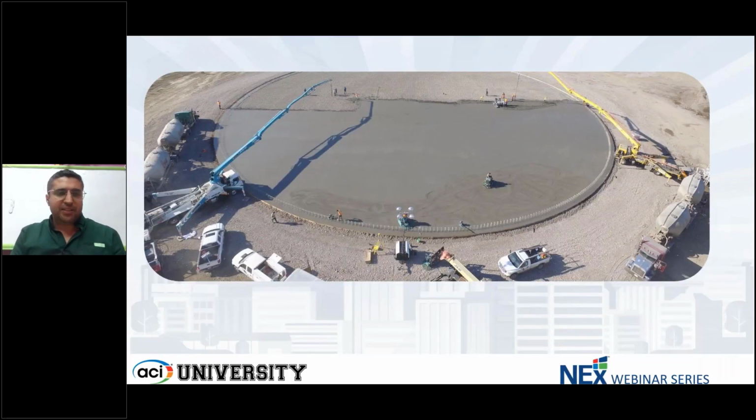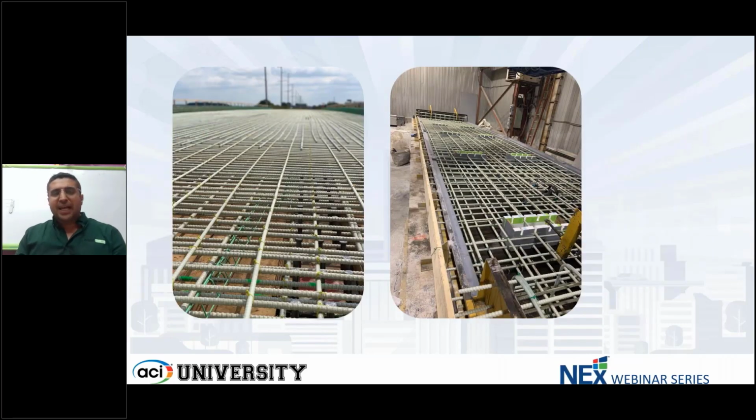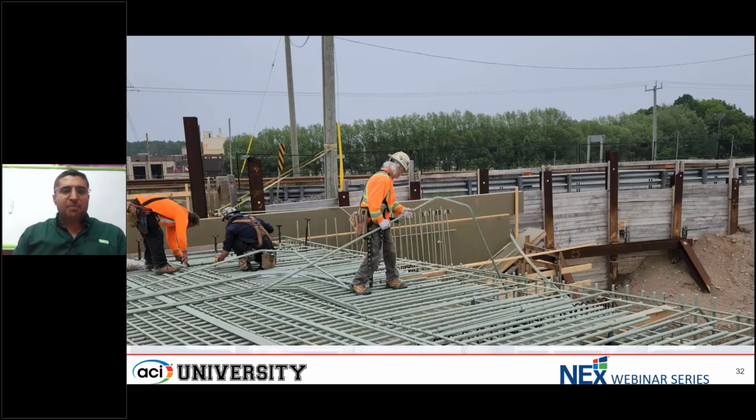More applications: 220 feet slurry tanks for biogas applications, animal waste, 40 feet high, pure ammonia and very aggressive environments reinforced with GFRP. Precast versus cast in place. Picture on the right side shows a precast bridge deck. Picture on the left side shows a cast in place. So there is definitely no problem using it in both precast and cast in place applications.